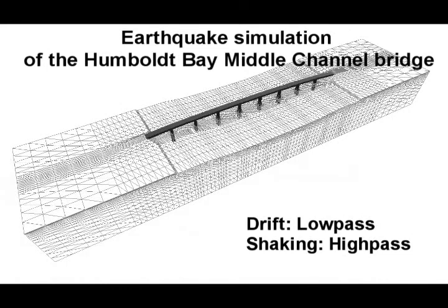The overall displacement can be decomposed into two main motions, drifting and shaking. Drift is a permanent deformation which is usually contained within the low frequency band and is the product of slumping, settlement, and/or heaving of the system. Shaking is the cyclic motion of seismic displacements contained in the high frequency band, seen as back and forth movement.